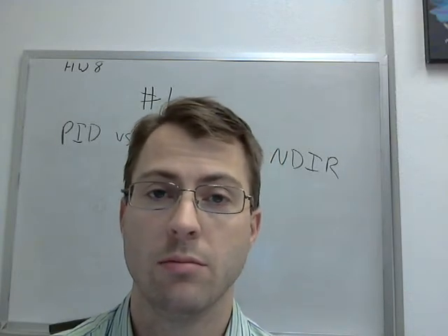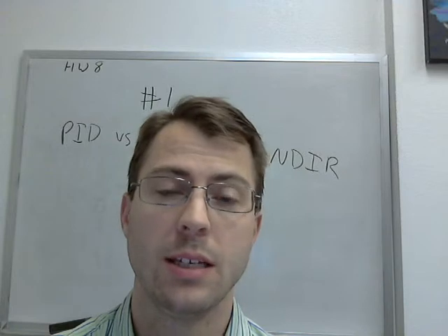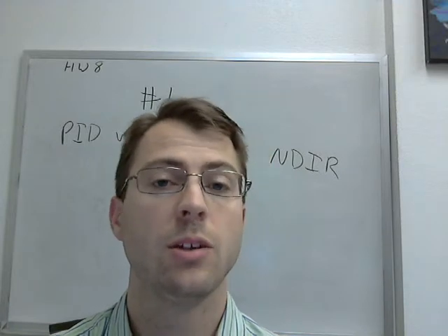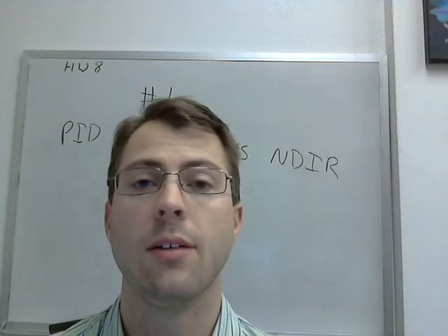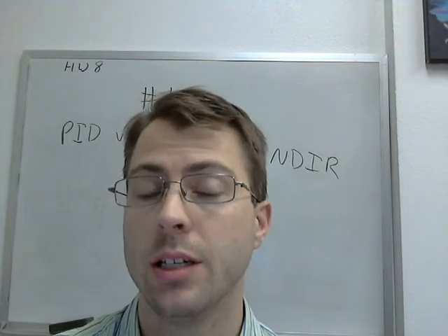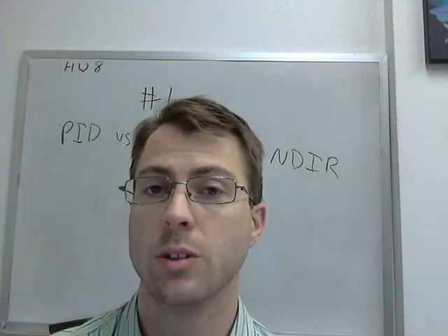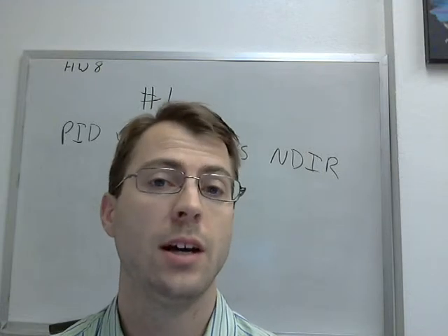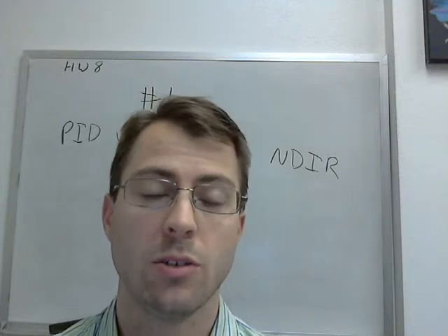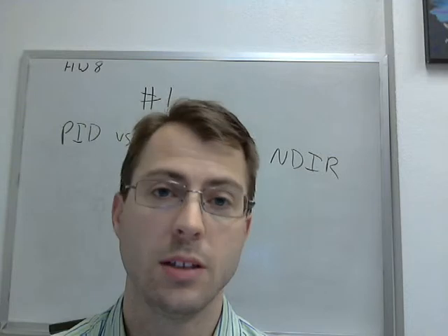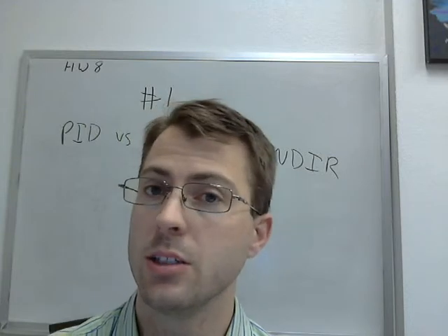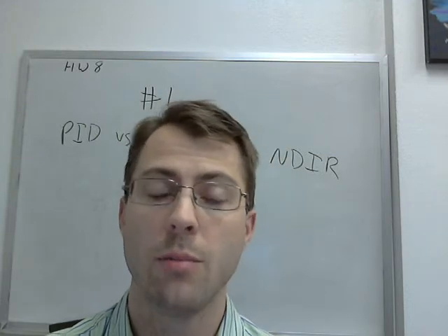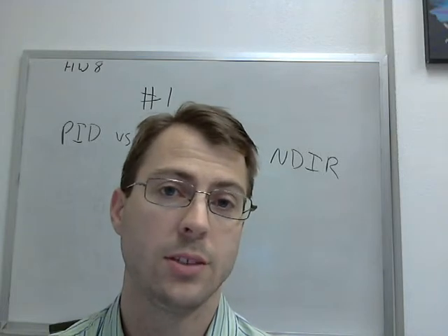The less it will respond to an FID, the more blind the FID will be. So if you have oxygens, if you have rings, if you have double bonds, you'll have a lower signal response from your FID. That is why carbon disulfide was the solvent of choice when industrial hygiene methods were being developed in the 70s and 80s, because the flame ionization detector was the primary detector on gas chromatographs.